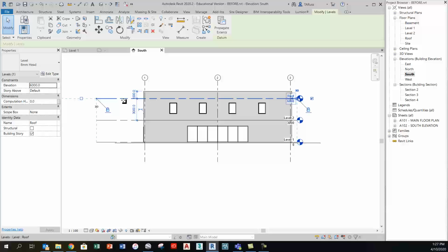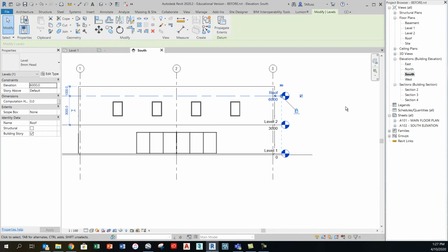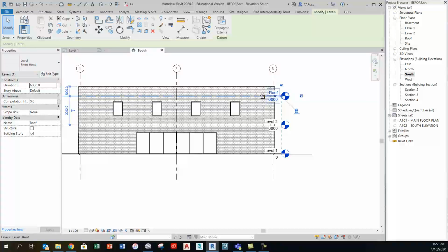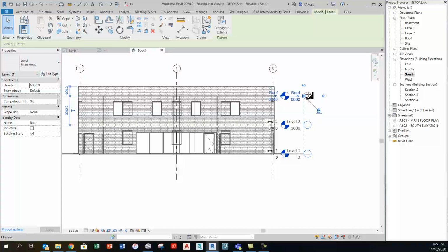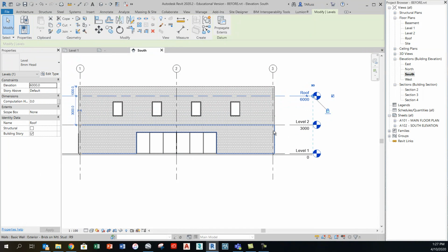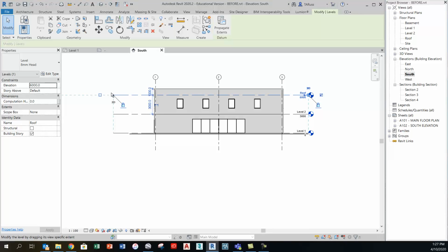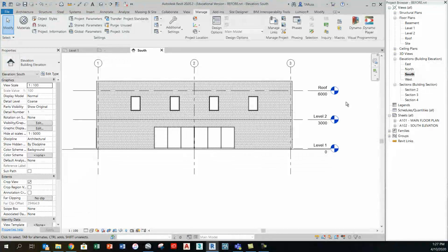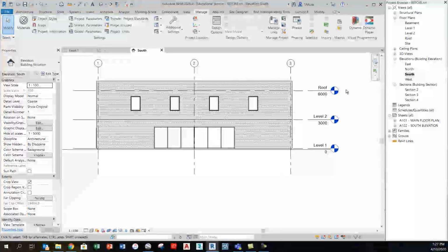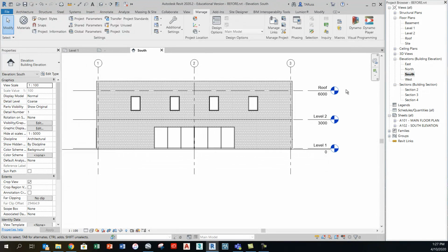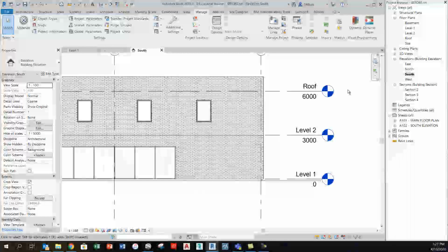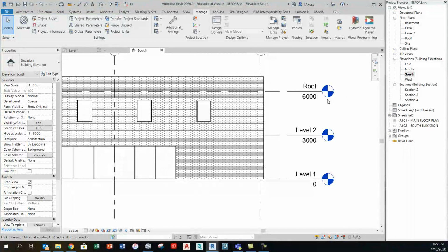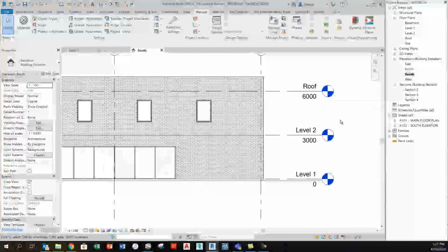Click on any one of, in this case, the 3 level lines, and you'll see right at the interface here of the level line and the geodetic symbol, I've got a little symbol that I can use to drag the text off to the right. So correcting that overlap, very important issue. It's a kind of sloppy default in Revit that we don't want to stick with. Having done that now, we can see something that looks a little better, but there's another correction I want to make here, and once again, this is just consistent with the theme, an oversized default element that we don't want to stick with. And the pattern for fixing this is very similar to what we saw with the grid symbols.